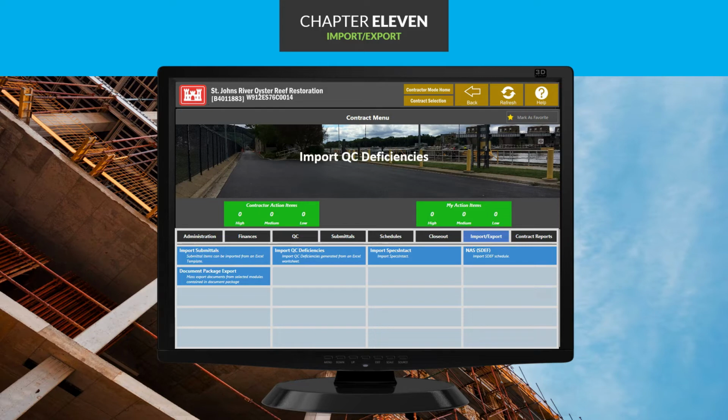The module to import QC Deficiencies provides you with the capability to import a deficiency list using a government-provided Excel template. A separate file must be used for each day's deficiencies. RMS 3 will automatically number the added deficiencies with the next available number in the QC Deficiency item sequence. I must stress here, the best way to log deficiencies is through the QC Daily Report.